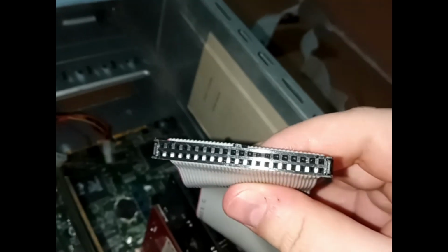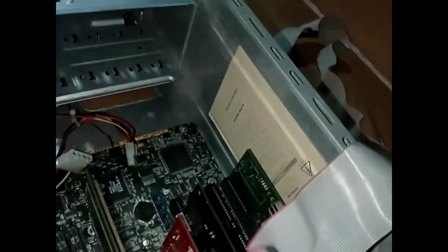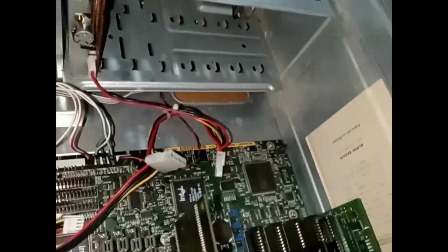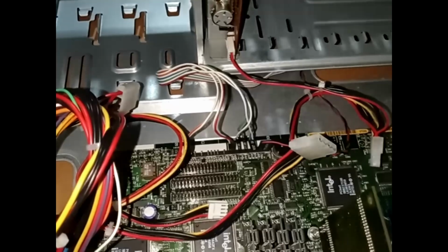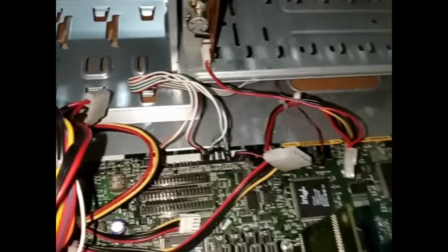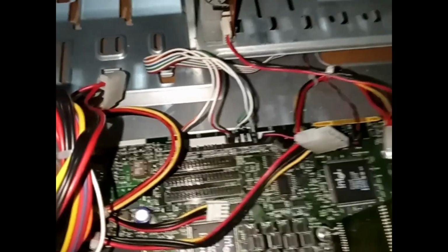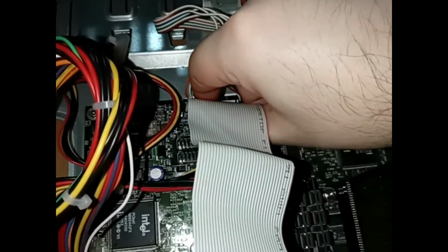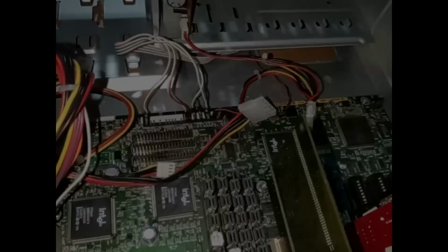And that missing hole is in the opposite side to the notch that the IDE cables have for the socketed connectors, which in this case tell us that the IDE cable has to be connected with the notch to the front of the computer. That's useful because the floppy drive cable usually matches the same direction for the connection.